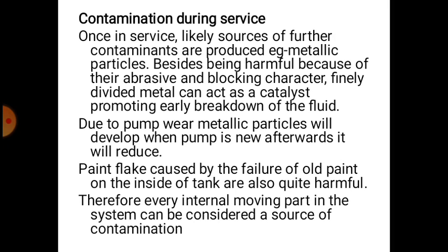Paint flakes caused by the failure of old paint on the inside of the tank, or paints which are not compatible with the fluid, are also quite harmful. As the machine continues to operate, moving parts naturally begin to wear and generate dirt. Therefore, every internal moving part in the system can be considered a source of future contamination, especially during the machine breaking-in or running-in period. Component housings continually experience hydraulic and mechanical shocks due to constant flexing from normal stresses and pressures.